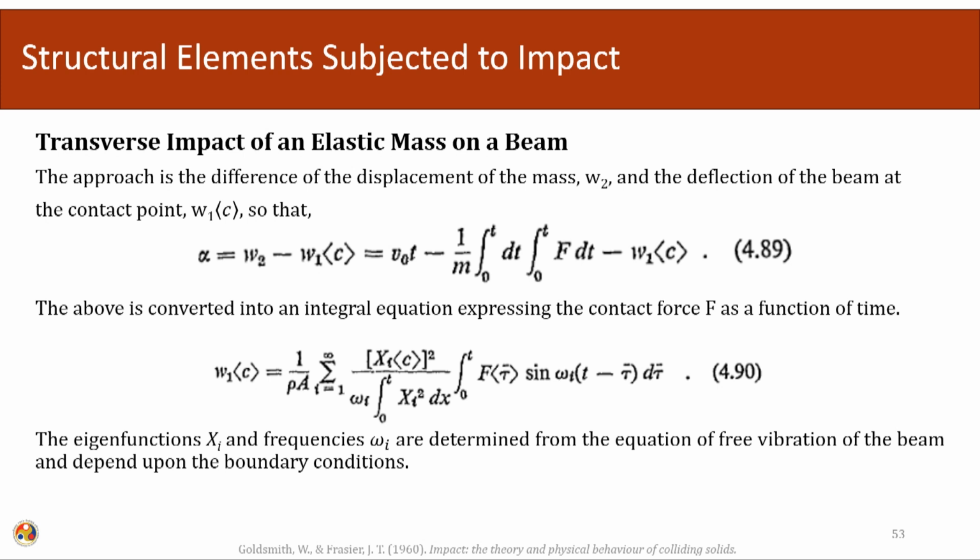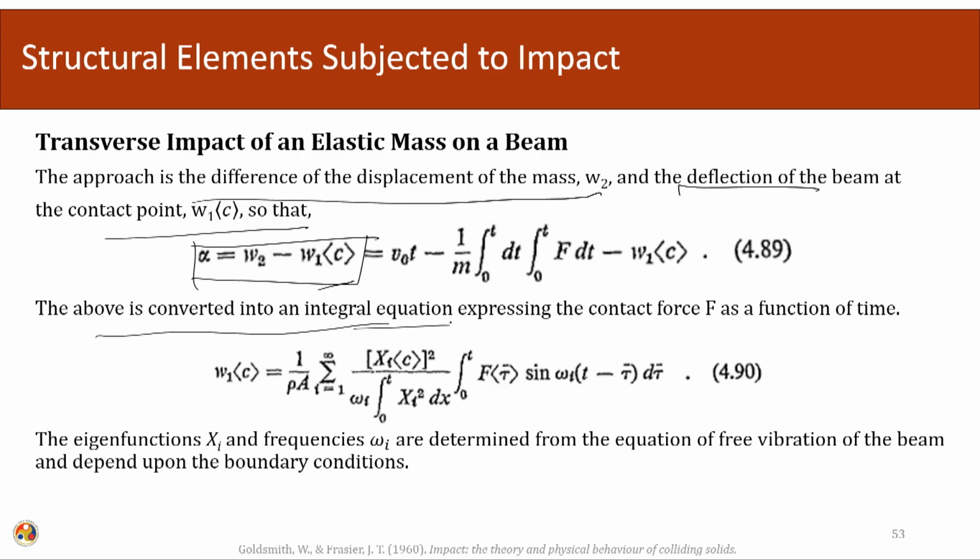In this approach, what is happening is that the approach is the difference of the displacement of the mass W2 and the deflection of the beam at the contact point W1. So, here we are formulating the problem. The above is converted into an integral equation expressing the contact force as a function of time.